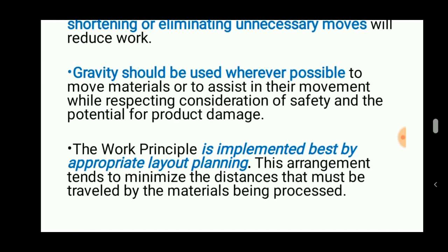Simplifying the process by reducing, combining, shortening or eliminating unnecessary moves will reduce work, and gravity should be used wherever possible. If you want to transfer products from an upper to a lower position, or within a pipeline, say a liquid must be transported from a height of 50 meters to the ground level, you need no pump for transferring the liquid from upper to lower.